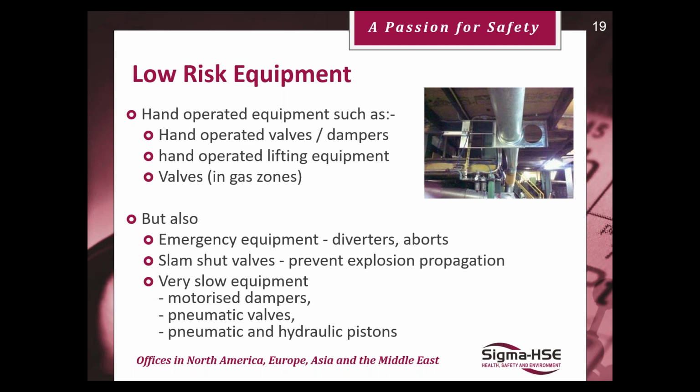So that's one benefit. But of course, if you want to do a NIRA for large equipment like a screw conveyor or a blending unit, typically ATEX rated equipment is usually 3 times more expensive, just a rule of thumb, than non-ATEX rated equipment. That's not to say that you shouldn't buy ATEX rated equipment. Of course you should, that's the legislation, but I just thought I'd mention that. Good practice is to always get the ATEX rated equipment.